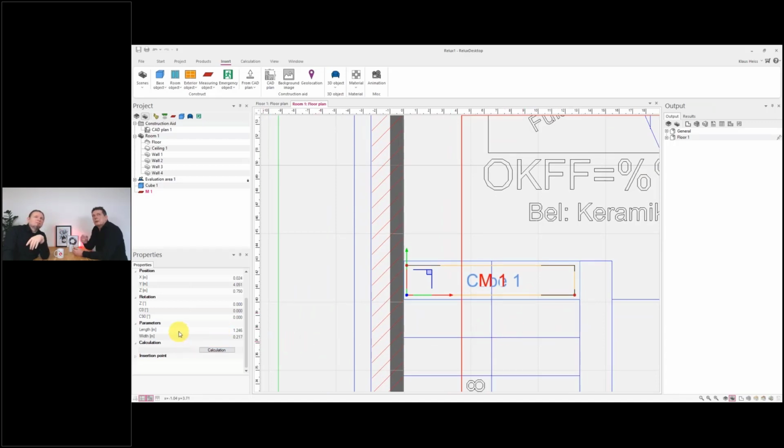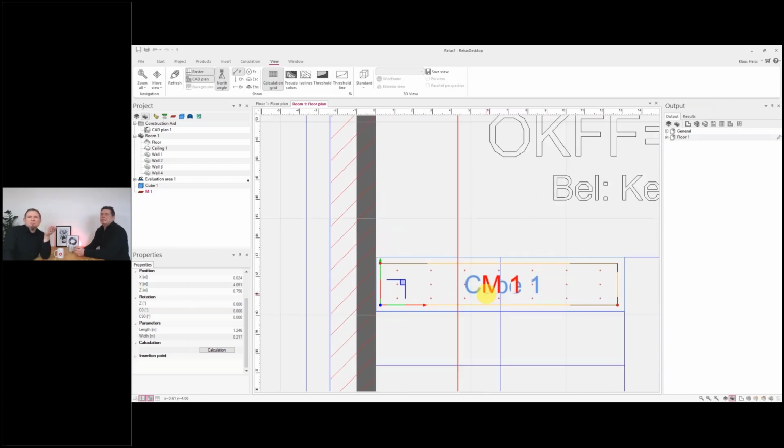I guess you can use the view and show the grid points. Yep, this is also possible. Yeah, here you can see the grid points. That's okay for me. We have some points, and we can later decide what you want to use them for. Also important is the height. We are at the moment at 75 centimeters. This is too high. I go for 20 centimeters. The stair is 17 centimeters, and I respect the measurement height with 3 centimeters in this case. Of course, you can also go lower or a bit higher. It's really up to you what you can argue.